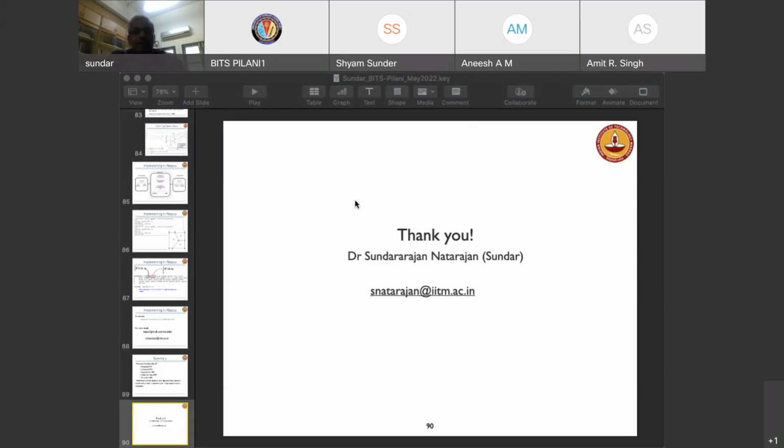Yes. So like you rightly said, we do use FEniCS. We have not used CalculiX, but its syntax is very much like Abaqus. We have also used Firedrake, which also looks like FEniCS. FEniCS is good and powerful in my opinion, but the disadvantage is that for now it is restricted to only triangular elements, and we don't get to the core of the code.